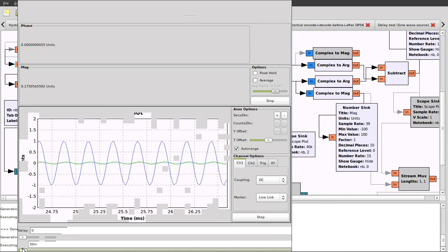So the fast Fourier transform is extracting all the bins that make up the complete transform, and then we have our little filter using the skip head and keep one in N, extracting the only one bin of interest, and you can see that then going through further calculations and then being shown here. The phase isn't changing except in those very final decimal places that we don't really have to worry about.